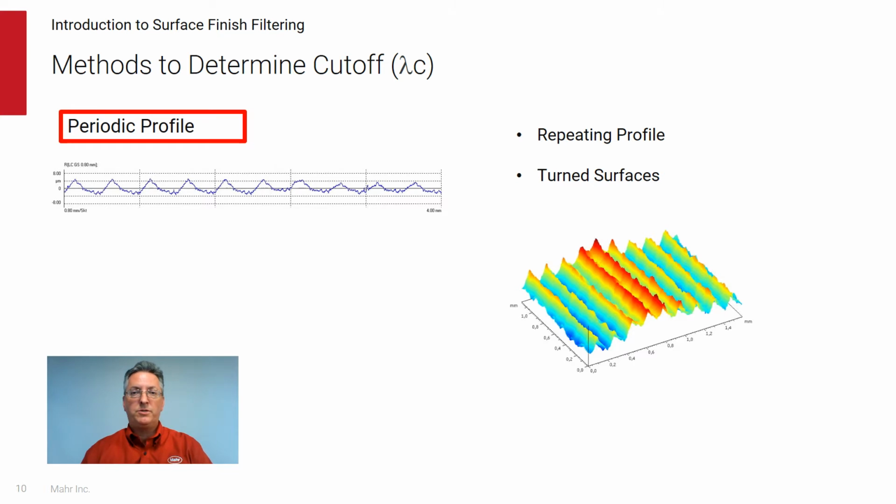Notice that on the 3-dimensional surface, there is a predominant direction of lay. The preferred direction of tracing is direction 1. If a trace were made in direction 2, then the repeating feature would not be seen in the roughness profile.